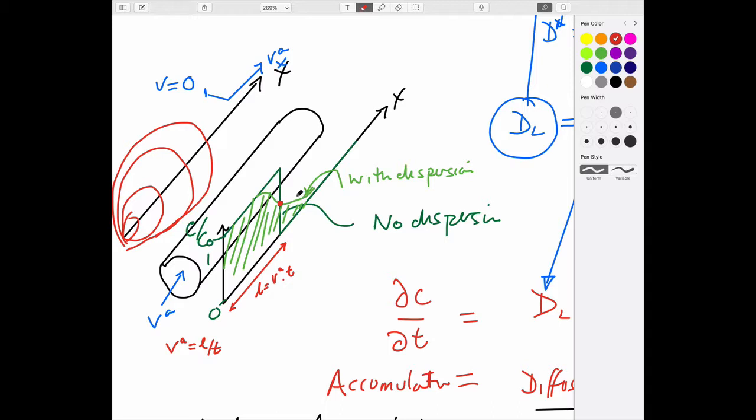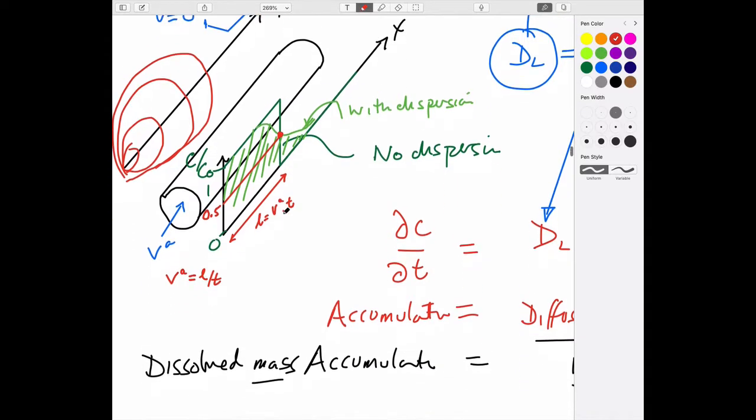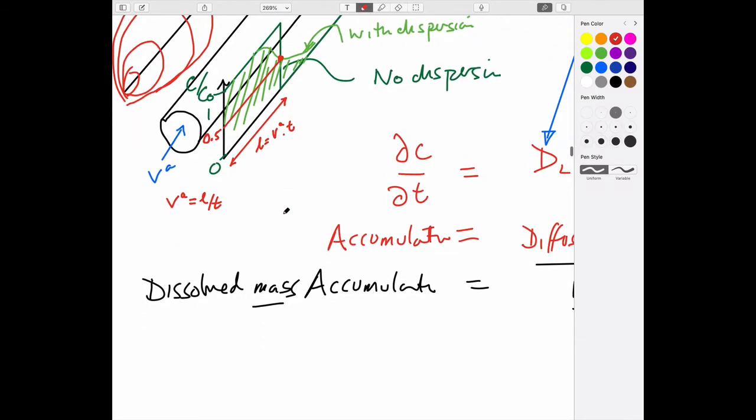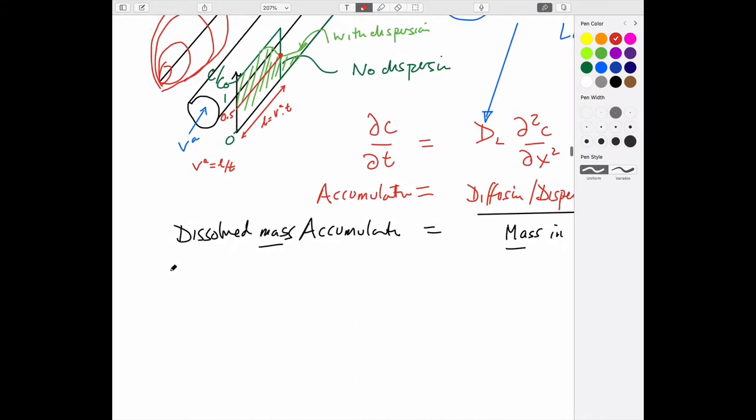If we had dispersion around this thing, maybe we could still take that as the 50% point. So in other words, where relative concentration C over C0 was equal to 50. So that's a convenient conceptualization that we might use. So there's, I guess, a couple of questions that we can ask, and I'll try and keep them on the same page. And I suppose one is, is L equals VT okay for estimating plume location?